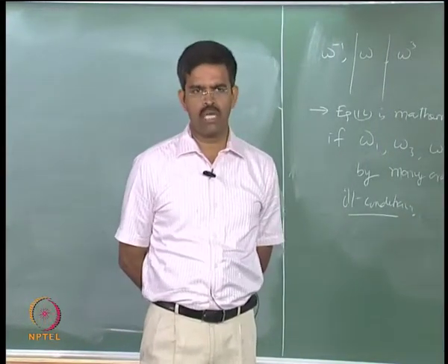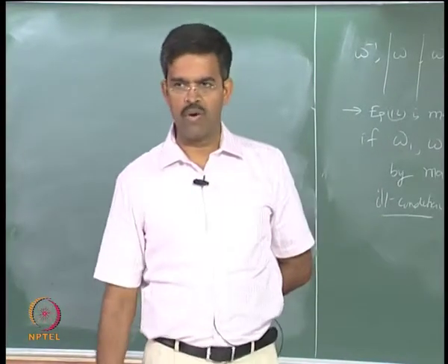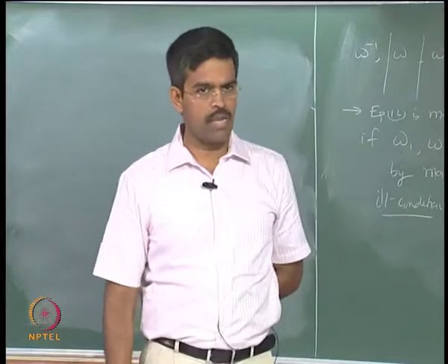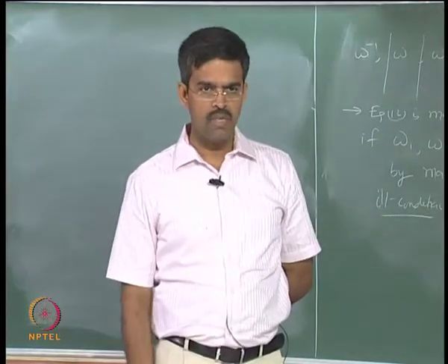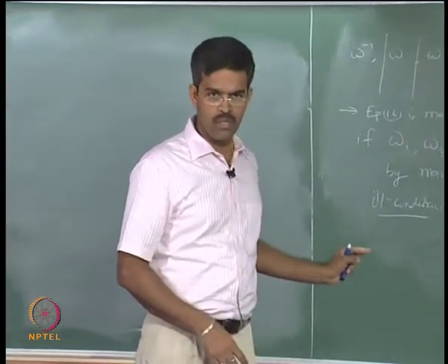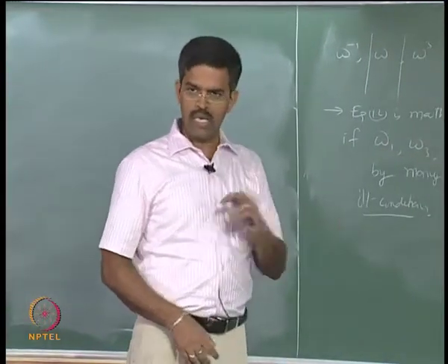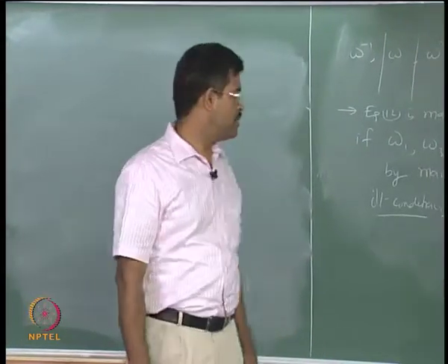So, if you are talking about, let us say, TMD, which we saw in the previous lectures of the same module, we have used unit mass dampers. There are many other ways by which one can control the responses; we have to play only with the damping matrix. So, estimation of damping becomes very important in the analytical as well as practical significance of offshore structures, okay.